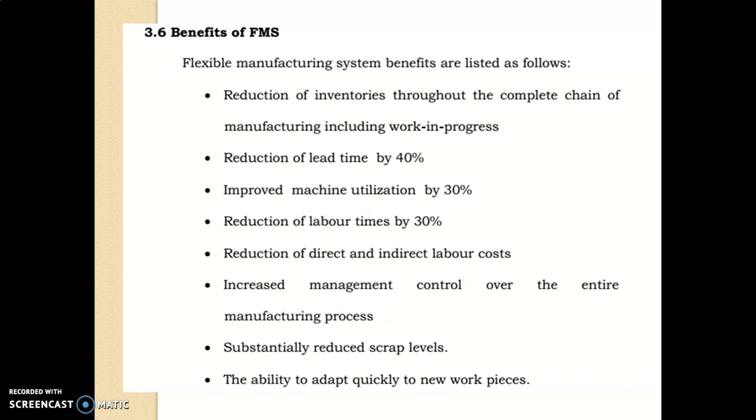And what are the benefits of flexible manufacturing system? The benefits are reduction of inventories throughout the complete chain of manufacturing, including work in progress, reduction of lead time by 40%, improved machine utilization by 30%, reduction of labor times by 30%, reduction of direct and indirect labor costs, increased management control over the entire manufacturing process, substantially reduced scrap levels, and the ability to adapt quickly to new workpieces.